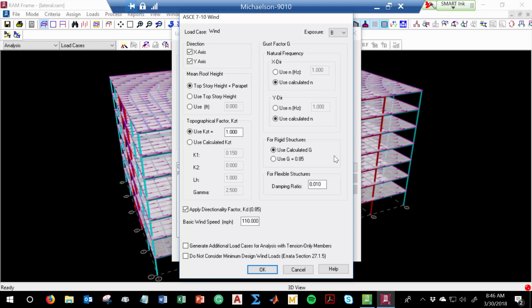Well, first off, we need our wind speed based on our location in the United States. Like for most of the United States, our design speed is around 110, 115 miles per hour, except for the coast. Why is the wind speed higher on the coast? What's that? Well, yeah, that's true, but there's another reason. What do you see out in South Carolina and Florida and Louisiana that we don't see as much in? There we go. I mean, but hurricanes are ocean-specific.